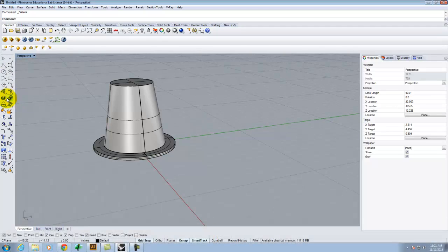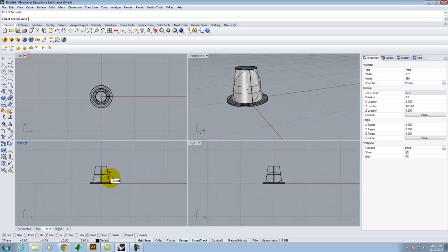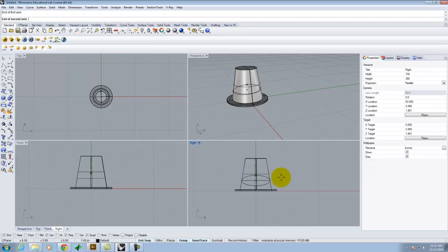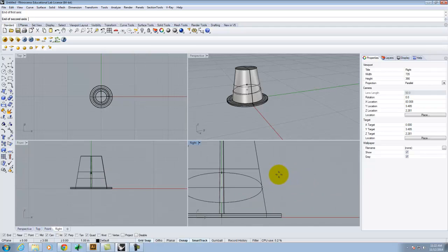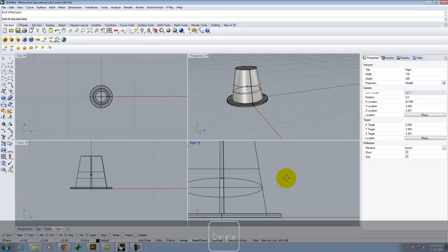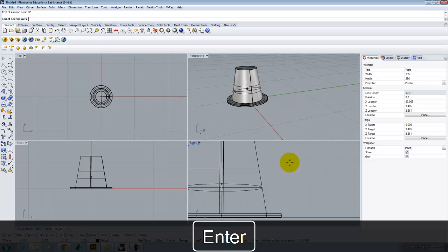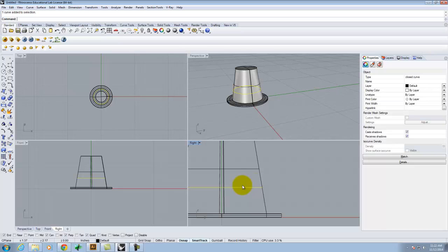All right, let me go back to my ellipsoid. I'm going to pick by diameter. So we'll say quadrant to quadrant. Right, I'm going to switch my views so that I can see kind of how thick that light bulb is. And let me turn off, for whatever reason, grid snap is on. Let's say I want it to hang down 1/2 inch or so. That works. So now I've created that little ellipsoid. I thought I did.